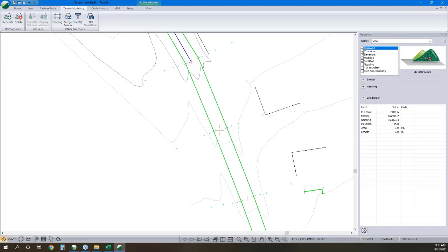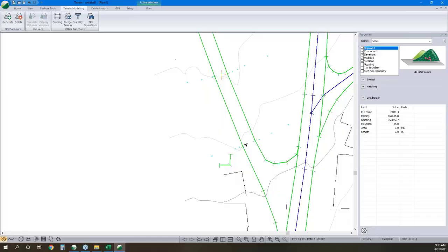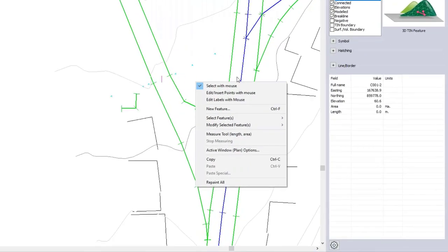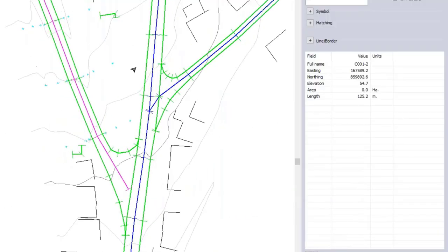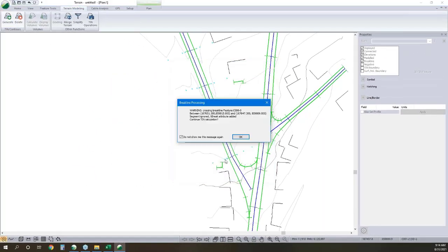So at that point, I'll hold in Shift on my keyboard, do our multi-select, and now I would normally use the hotkeys, which would be Control Join to join those, but we can come in here and click Join as well. And we can click Model again and update that surface.